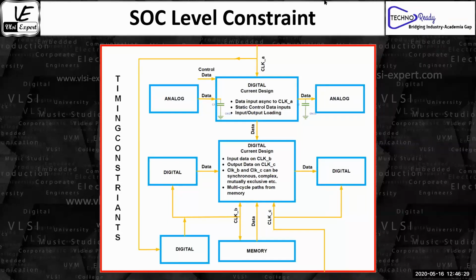So clock A is a 1 nanosecond repeated period clock, and clock C is some 500 megahertz clock, but there is no timing relationship between the two. When I say no timing relationship, they are not driven by the same source. So in phase, they can be as far apart as possible, or they can be shifting. They're not driven by the same thing, so you cannot say any particular relationship between the two.